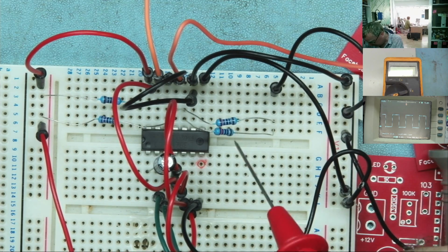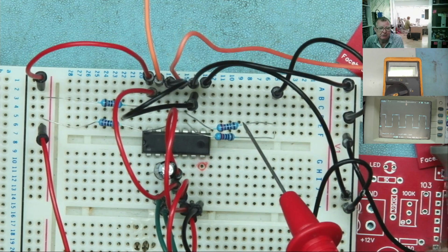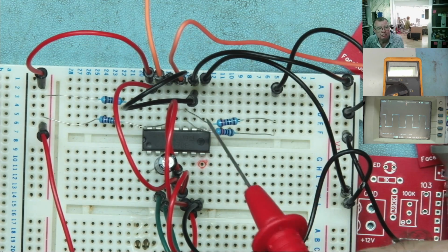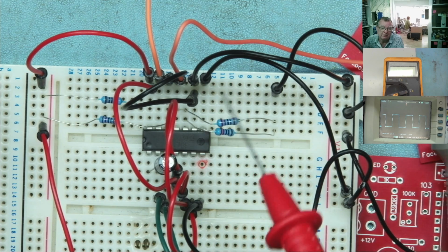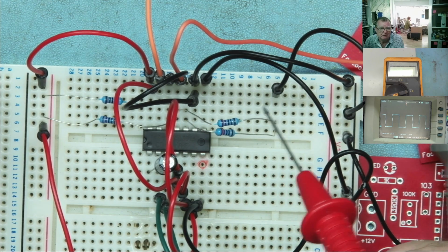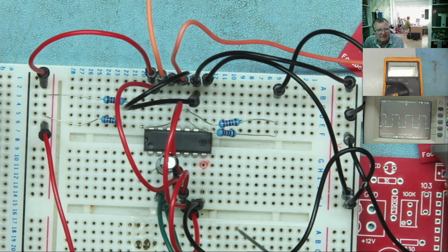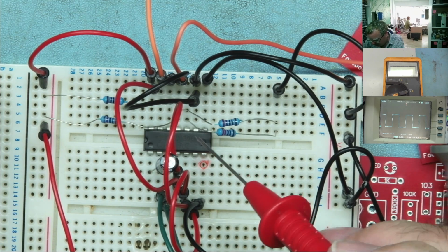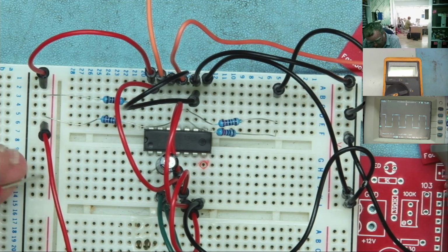Right guys, so I've taken the LEDs off. I've connected a resistor, these are 2k resistors, to ground and also to the supply voltage from pins 10 and 11. These pins were driving the LEDs through 470 ohm resistors, so they should be quite happy with this resistance. I'm just interested to see what we see output on those pins. Okay, let's have a look. So obviously there's no LEDs now, but we should see the thing oscillating on the scope as before.